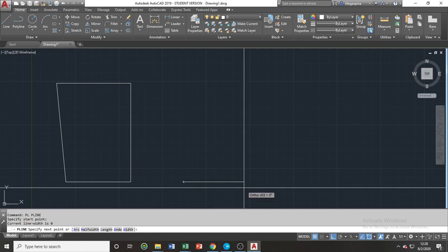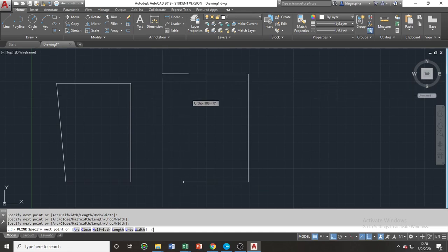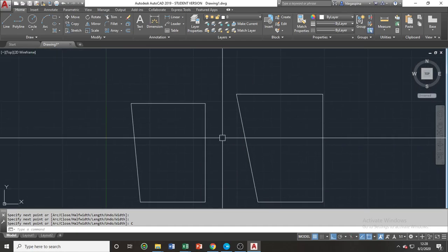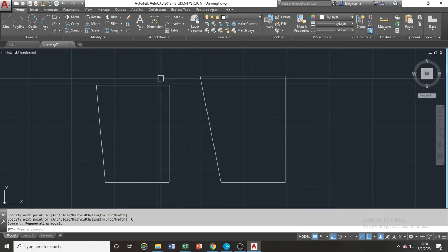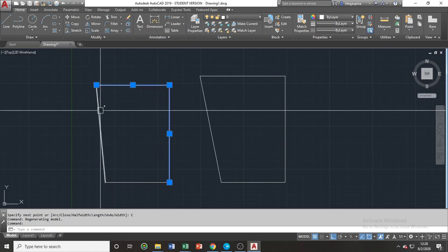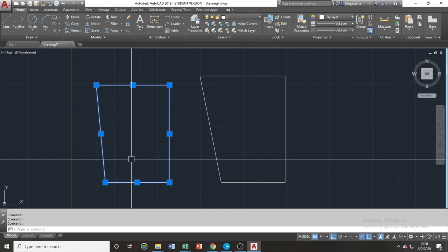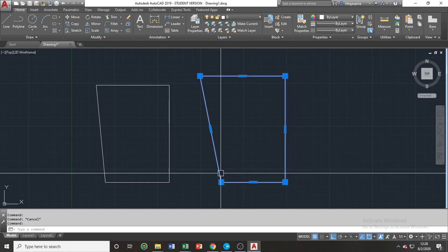So you can specify fixed angles, or you can specify a fixed length for your polyline segments. The difference between creating polygons using the line command and the polyline command is that the segments of the polygon using the line command are independent from each other, while the polyline segments are all joined within one selection only.